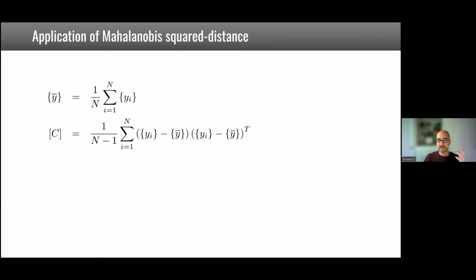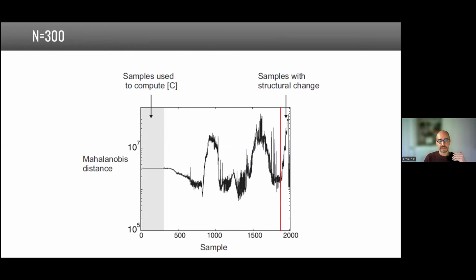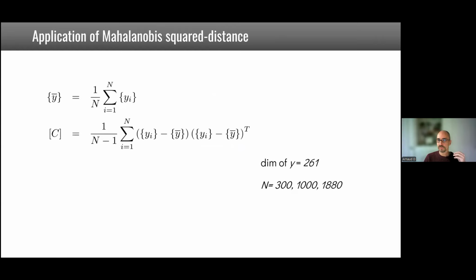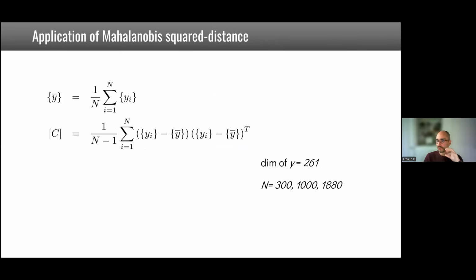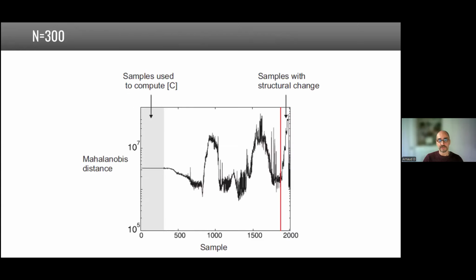And we can compute the mean, and we can compute the covariance matrix. But in the covariance matrix, we can choose to put all the data of the undamaged sample or only part of it. So I just want to illustrate the effect that it has. And from that, I'm computing this Mahalanobis distance. So remember, the Mahalanobis distance is supposed to filter out naturally the changes in the data that you trained it for, because of this 1 over sigma that comes into the distance.